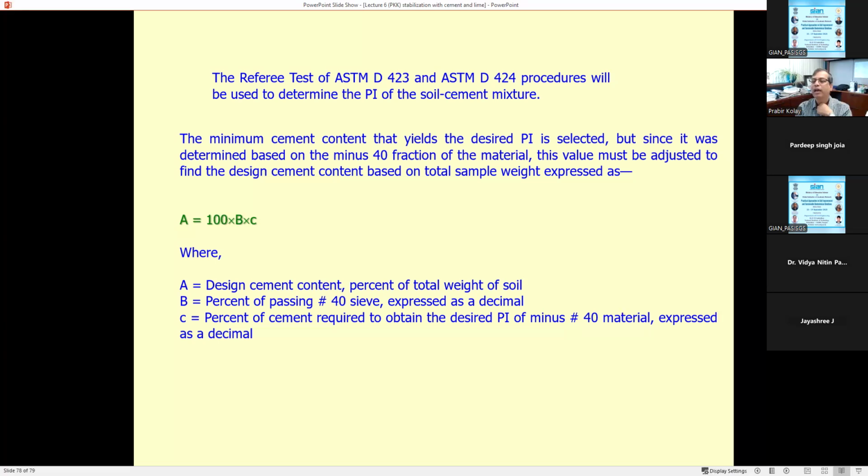Regarding lime stabilization of expansive clay having higher plasticity, the addition of lime leads to higher moisture content compared to the untreated. Yes, if it is expansive soil and you use lime, then obviously the moisture content will increase.